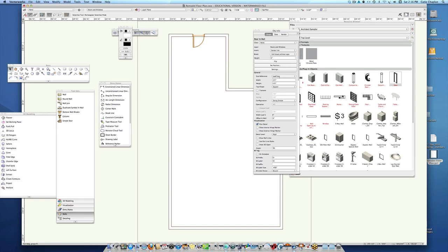And let's set its size. So from the sketch, it's a 3.0 door, otherwise known as 36 inches. Its height is 6'8". It's a standard door. Top shape is square. That's fine. Simple swing. And we've got the correct size and the correct swing. Let's set it into position.